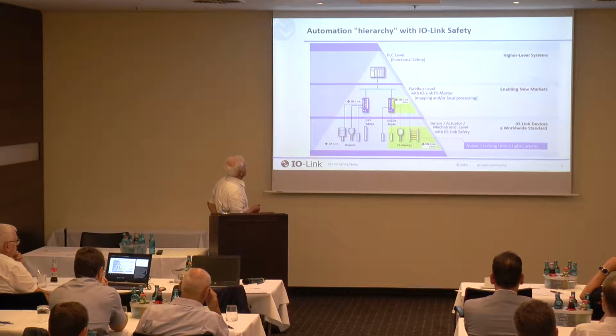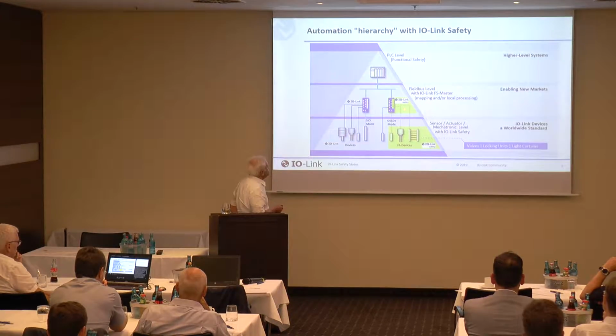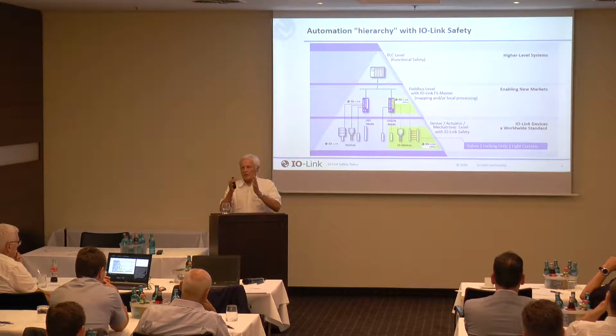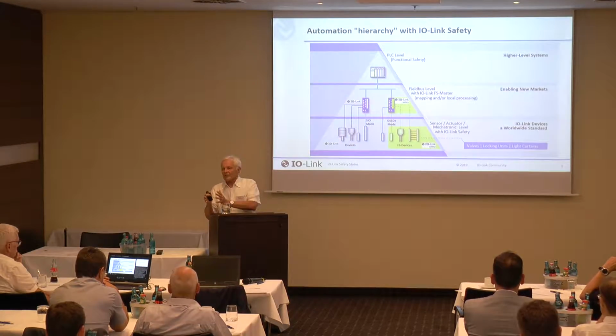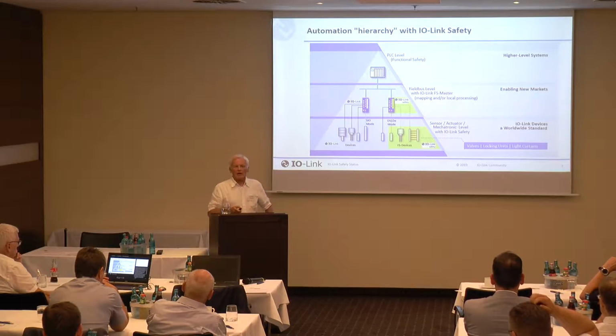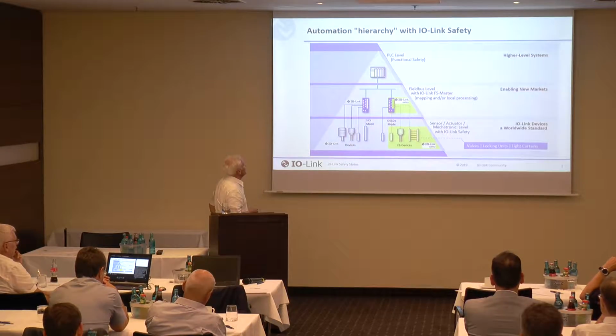Okay, this is the hierarchy we have already seen, and there is no separation here. This is the pyramid, and in the pyramid we have the standard IO-Link devices, like masters, and here the IO-Link safety master can drive the safety devices, but in addition, standard devices. So the safety master can be used for standard, non-safety, and for safety devices. So that should allow for easy applications and cost-efficient applications.